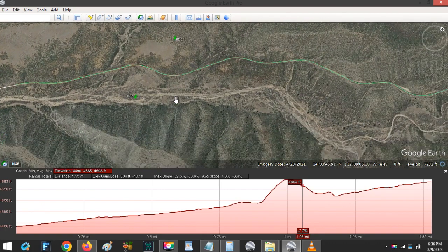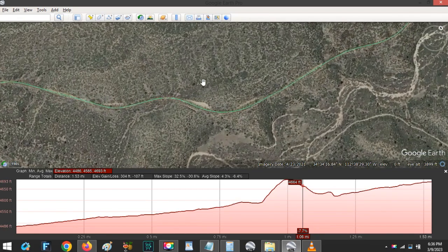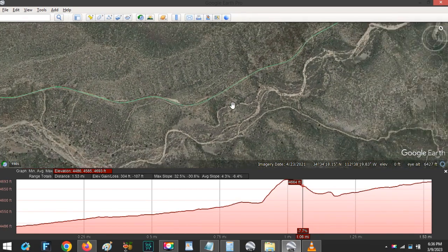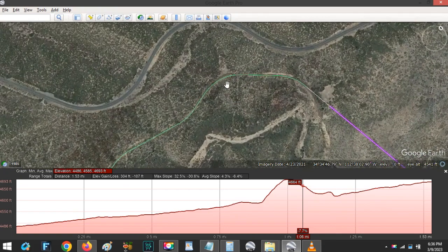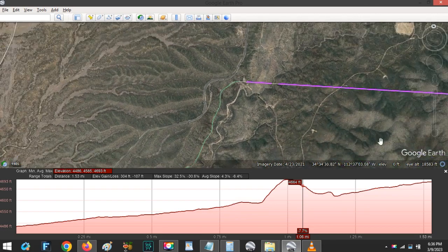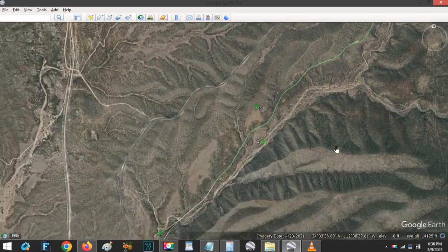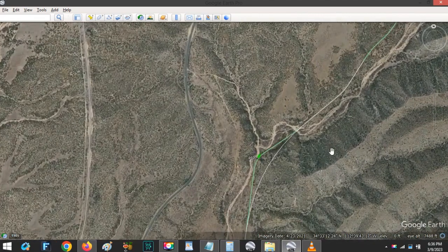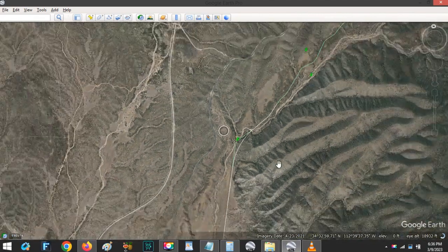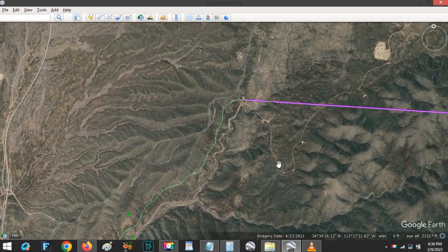It doesn't get too curvy until you get right up here. That looks like quite a tight curve in the reverse, and these we know because I've measured them are 500-foot radius, so you'll be going pretty slow when you get up there in any case, but it'd be possible to mitigate that some with a tunnel there. It might be pretty expensive, but then you get a better alignment.